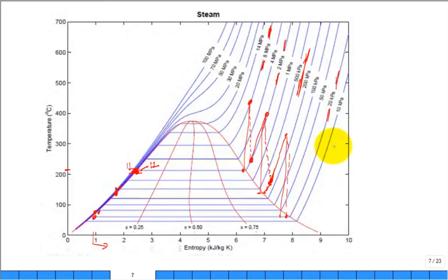That's right. So it'll be irreversible expansion through that throttling valve. So S is going to increase going from 12 to 13, and you're dropping to the lower pressure. So it'll be somewhere like that. It's at that 300 kilopascal pressure, isn't it? So we'd like to put a dashed line in there. It's not straight down. It's over a little bit to the right. Makes sense?